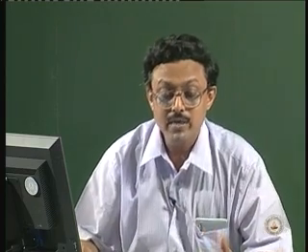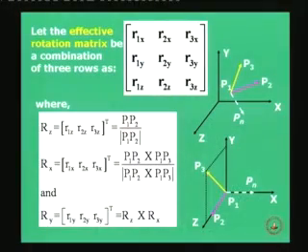To implement this concept, we will look back into the equations, where the corresponding form of the coefficients of this combined or effective rotation matrix is given, and we will start with the bottom row, the last row of that matrix, where I define Rz to be a vector of the last 3 coefficients of the last row elements of the matrix, given by what? It is nothing but the unit vector along P1, P2. So, if I put the elements of the last row equal to the unit vector along P1, P2, that will help me get this vector aligned with the z axis after transformation.